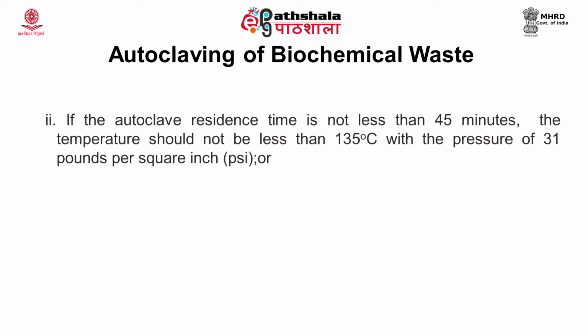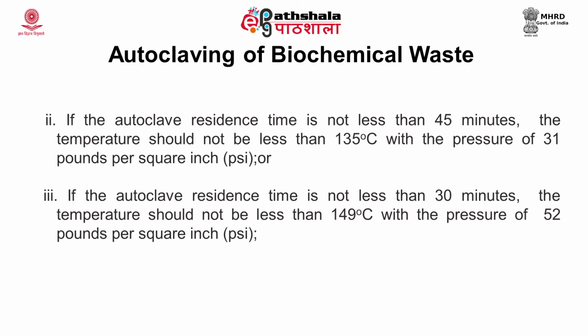If the autoclave residence time is not less than 45 minutes, the temperature should not be less than 135 degrees Celsius with a pressure of 31 psi. Likewise, if the autoclave residence time is not less than 30 minutes, the temperature should not be less than 149 degrees Celsius with a pressure of 52 psi.